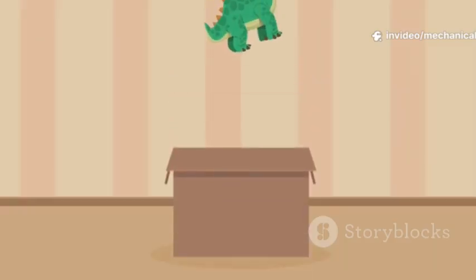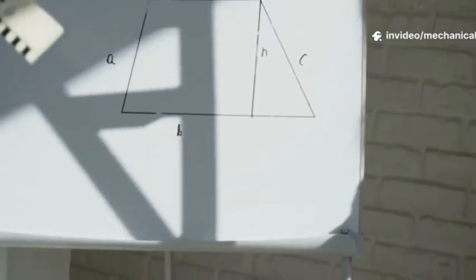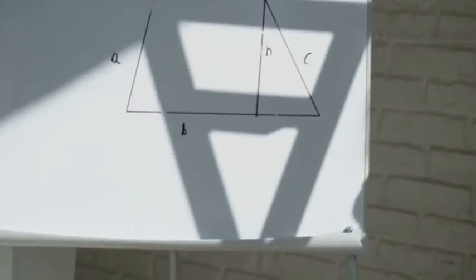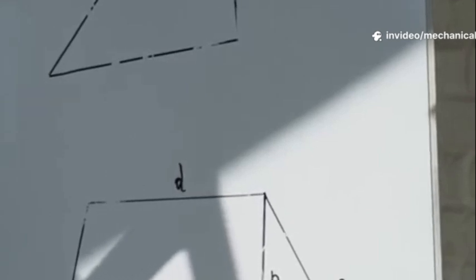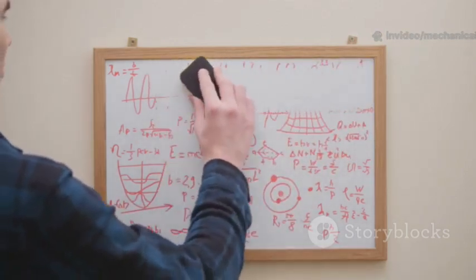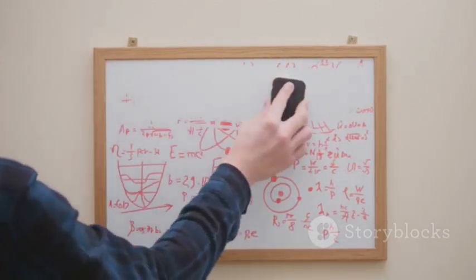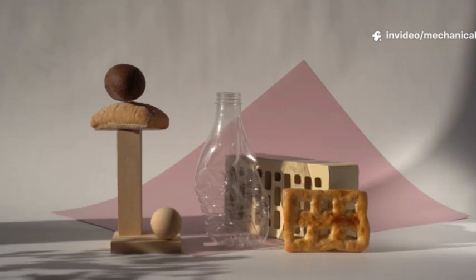Next, let's tackle a box sitting on a ramp or an inclined plane. Gravity still points straight down, always towards the center of the Earth. However, the normal force is now angled, perpendicular to the surface of the ramp. And if the box isn't sliding down the ramp, static friction is acting, pointing upwards along the ramp's surface. While each scenario might appear different at first glance, the fundamental steps for creating a free body diagram remain the same.